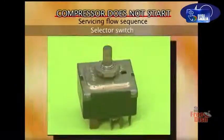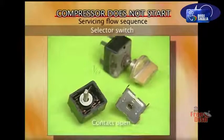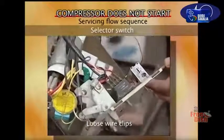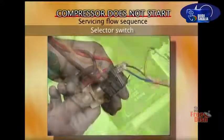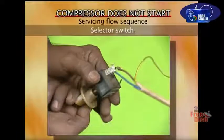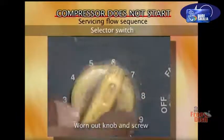Check the selector switch. The selector switch contacts may be open. A loose wire clips. A defective selector switch. Worn out knobs and screws. Check wiring.